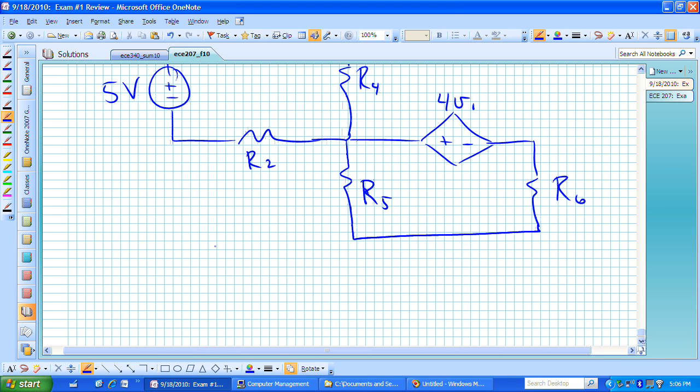And we have our current source, but remember we're going to get rid of that particular source. And what does it mean to eliminate a current source? If we want zero current to be flowing, then to eliminate a current source we actually remove it or open it up. And now what we have is the following circuit.